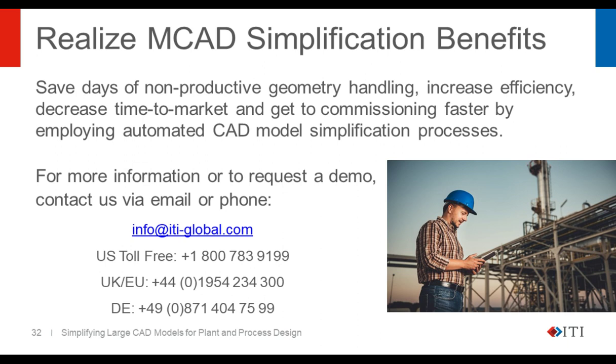Although CADfix normally focuses on processing solid models, we also have support for faceted model definitions. So where a model has been tessellated for export to a plant design system, we can read those faceted models, simplify them by reducing the triangle count, or we could export a mechanical CAD model to a lightweight faceted format, such as STL, FBX, or DWG faceted. So I think we cover most of the mechanical CAD formats and derivatives that you'll need.